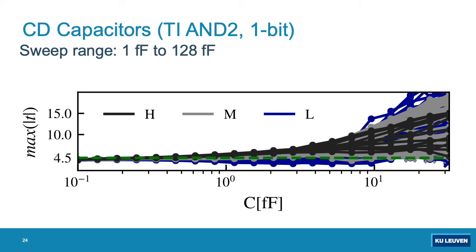We then repeat the experiments for the 3-share threshold implementation of the N2 gate, focusing on the many cross-data capacitances that it has. While other observations hold, we add one more consideration. Apart from the levels of leakage being slightly lower than for the small XOR gate, we also split the capacitances into 3 risk groups, calling them high, medium, and low. We draw the lines between the groups somewhat arbitrarily, but the main message is the following.